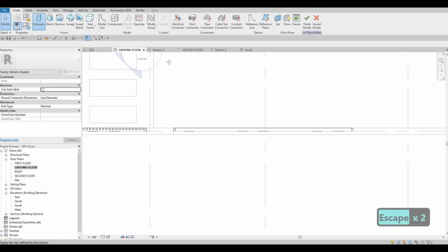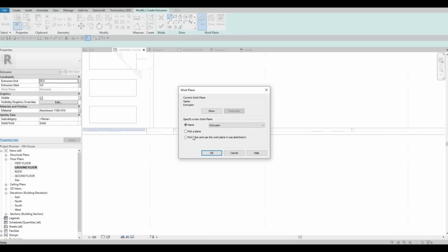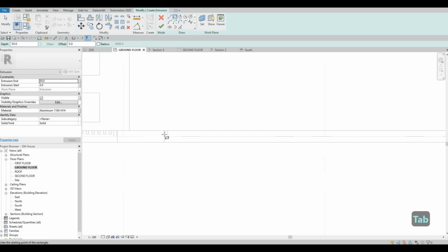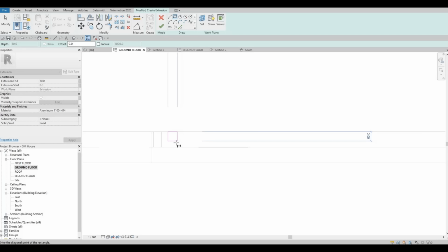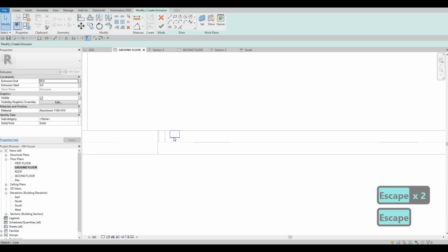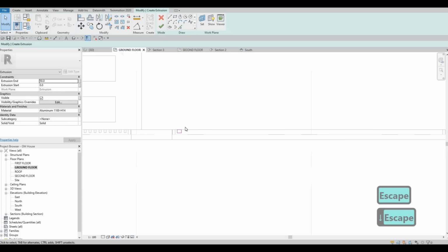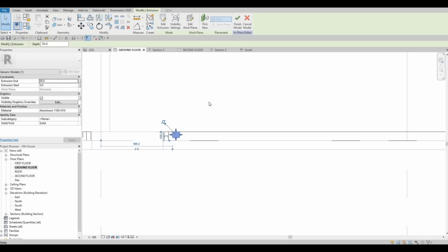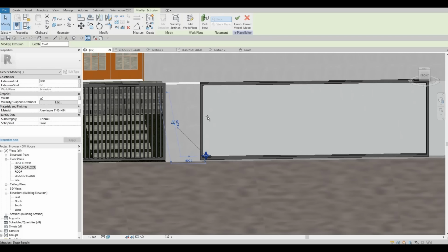And then create an extrusion again, set, pick a plane, which is spacebar to change, and then there we go. Let's add it right there, similar to what we did. We can make it a little bit big just to change it up. And then here we could just click on finish, go to 3D to stretch it out before we do an array.